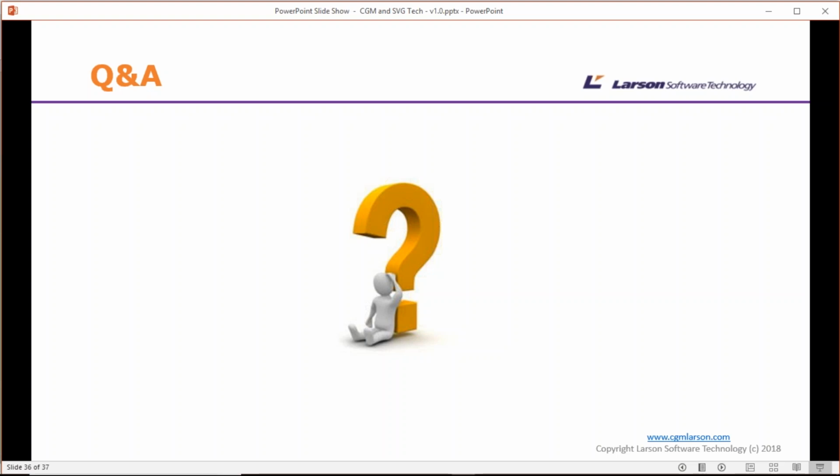Yes, I do. I see the questions here. The first one pertains to the segment we did on the BizX transform and hotspotting, and says, can the hotspotting include outline text? By that, I assume you're referring to text that's stroked out or made up of vectors rather than actual fonts. And the answer is yes. In the transform, if it can't recognize any text in a vector drawing, it'll employ some OCR to try and recognize the text too. So the answer to that is yes.